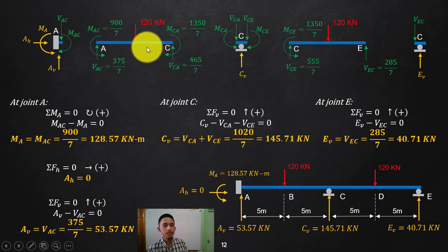Now this is at point A. So transfer that one at support A, exactly point A. This moment is originally counterclockwise, so that will go clockwise this way. That shear is going up, this will transfer going down. So now, of course, using your equilibrium, summation vertical, summation horizontal, summation moment, you will solve the unknown reactions. So this is now the end step.